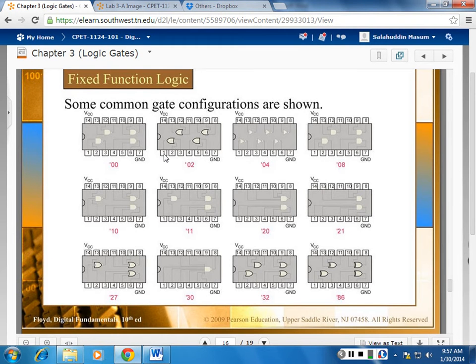So you always want to check the layout. Your schematic has most of the information, but in some schematics, we intentionally did not mention the pin numbers. The idea was to make sure you can find it out. We can tell you everything, but that will not help you. We did not mention which gate to use, so you can choose any of those out of 5 or 6 or 2 or 3. You decide which one you use and write down the pin numbers in the schematic. You can take a printout, write down the pin numbers, and then start running the wire.